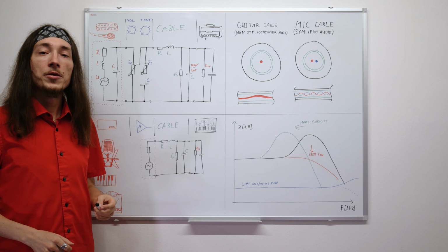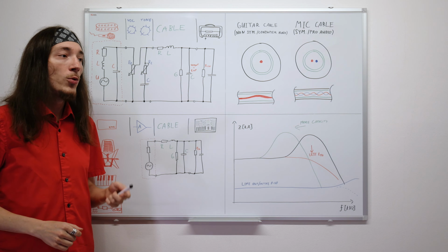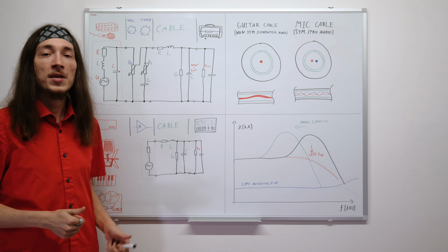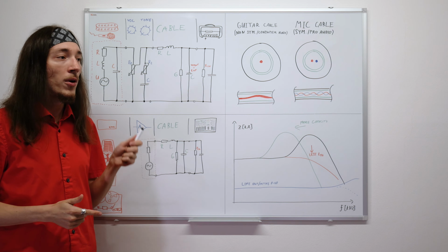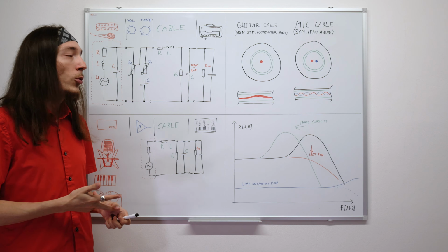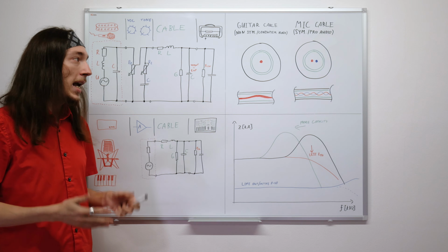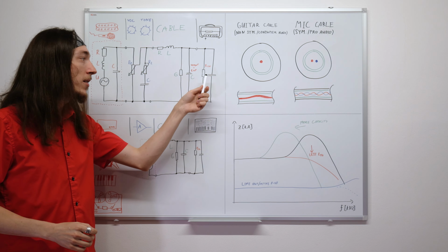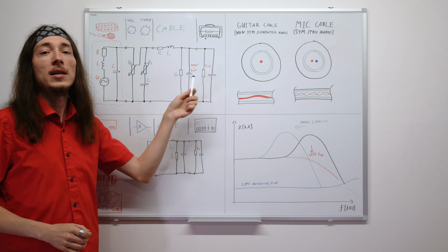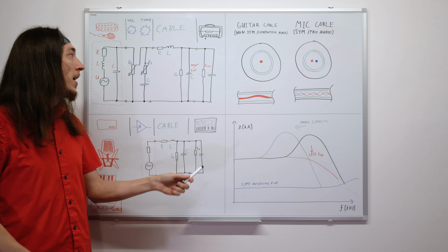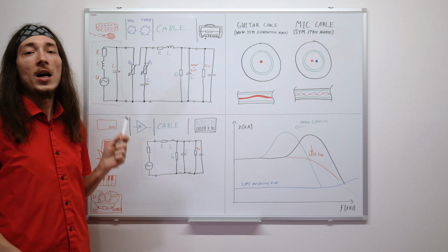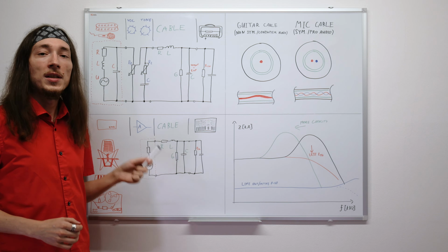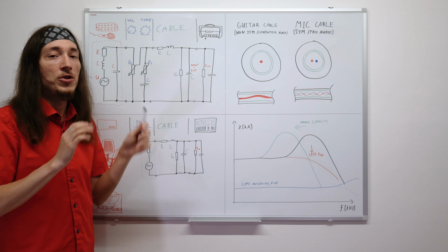So now I would like to talk about impedance matching, and we are not talking about radio frequency stuff, digital stuff or power amplifiers. We are talking about signal level and audible frequencies. Empirically, this load resistance should be at least 10 times higher than the output impedance of our signal source, so the signal source doesn't see that much load.